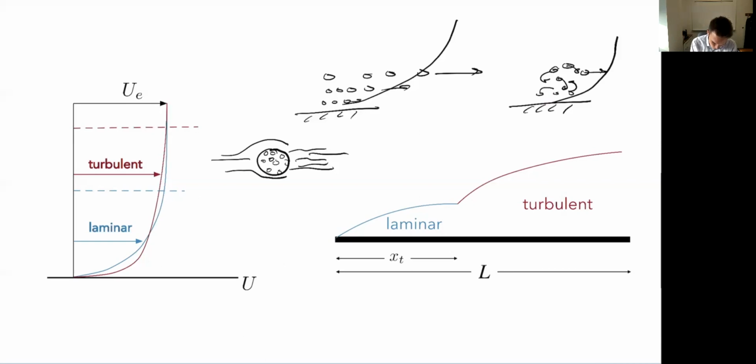For an airfoil shape, which is not quite a cylinder, ideally, if I'm at low angles of attack, I want lots of laminar flow. That has low skin friction drag, nice and smooth. That's why you'll see with a sailplane or a performance yacht, really smooth, polished surfaces, so I can have nice laminar flow and low drag.